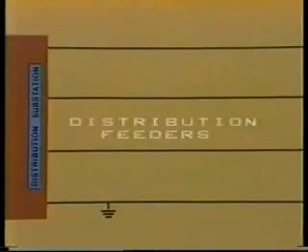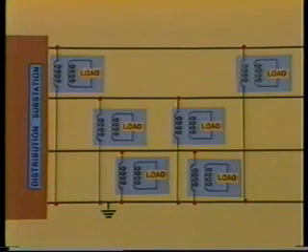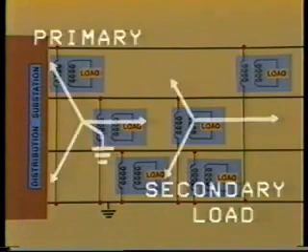The same problem of floating neutral can occur with single-phase loads which are spread out along the line. The single-phase distribution transformers are connected to different primary phases in an attempt to balance the load. Electrically speaking, it looks like an unbalanced YY transformer connection. Therefore, the primary neutral should be grounded.